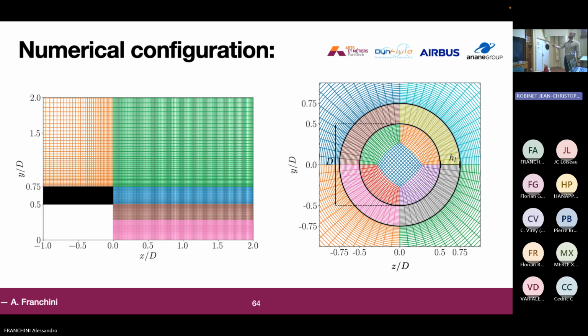So the boundary condition in the nozzle is the one of an adiabatic nozzle lip. Here we have the inflow. We don't model the inside of the nozzle since it has been shown in the literature that it is not very important in order to select the frequency of screech, and it's not important in the actual feedback loop. So we just put a supersonic inflow of Mach equal 1 at x equals 0 here.